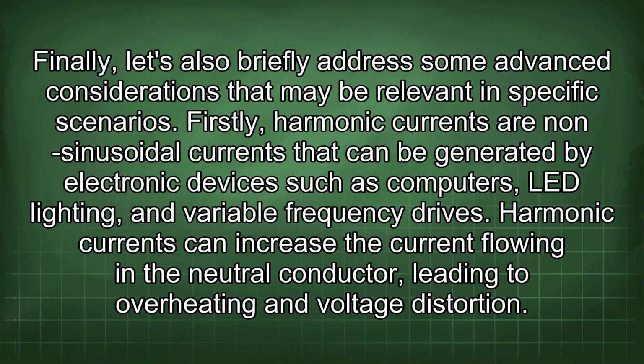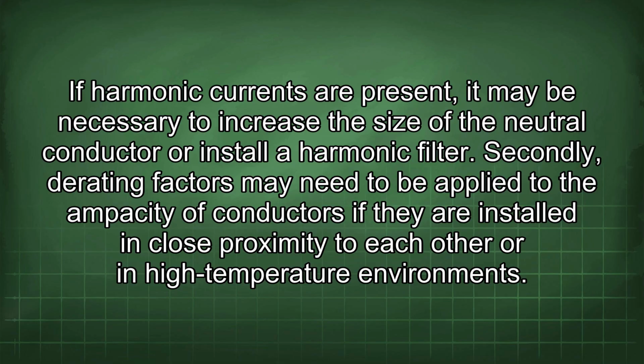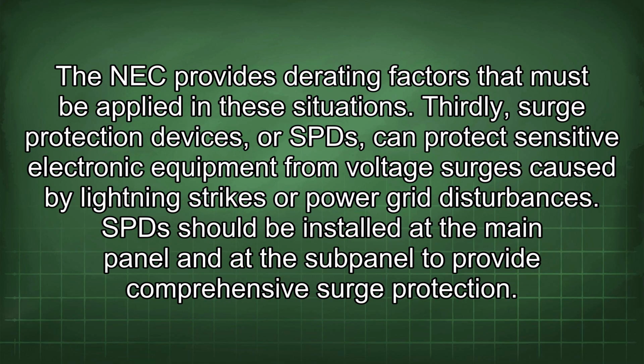Firstly, harmonic currents are non-sinusoidal currents that can be generated by electronic devices such as computers, LED lighting, and variable frequency drives. Harmonic currents can increase the current flowing in the neutral conductor, leading to overheating and voltage distortion. If harmonic currents are present, it may be necessary to increase the size of the neutral conductor or install a harmonic filter. Secondly, derating factors may need to be applied to the ampacity of conductors if they are installed in close proximity to each other or in high-temperature environments. The NEC provides derating factors that must be applied in these situations.